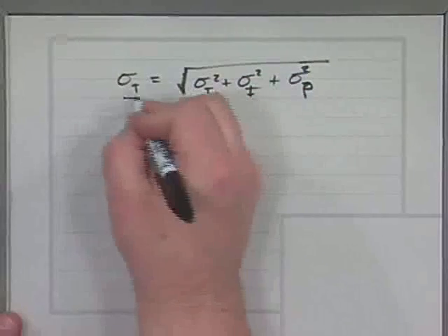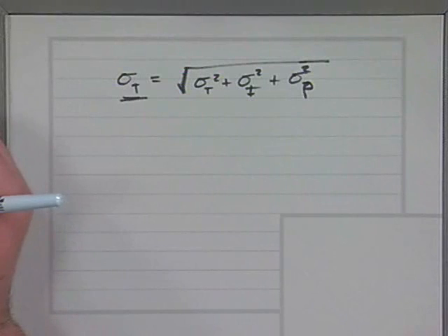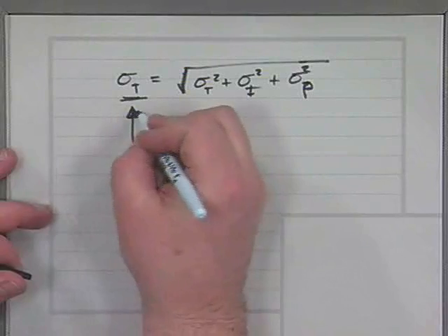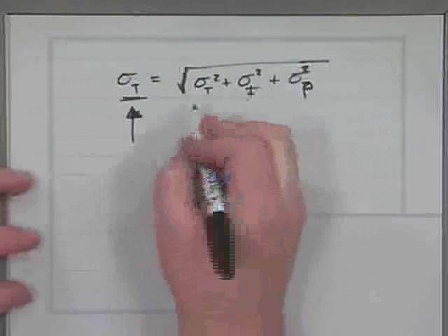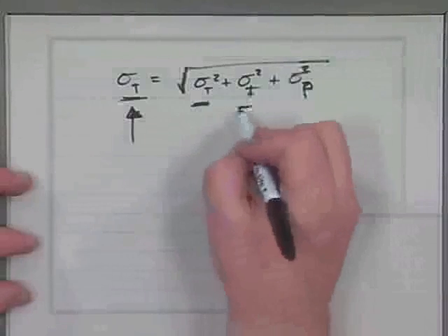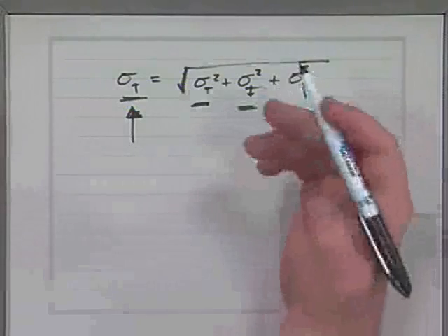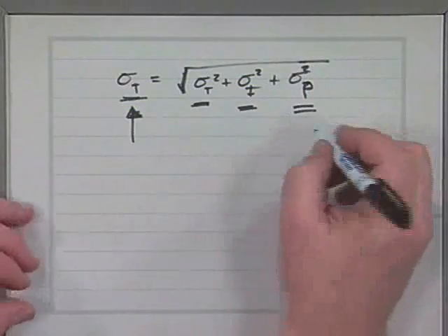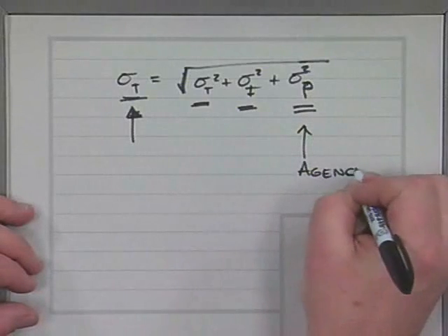So the total variation that's being measured on any test, if you go to the lab and you take a cylinder, you test that cylinder, the variation that you're bringing out is this particular variation here. When you run the standard deviation on the compressive cylinders that you get, that's made up of the variability that comes from the testing machine, the inherent material variability, the fact that concrete is heterogeneous, you're testing it with aggregates on a very large scale, and the production variability.